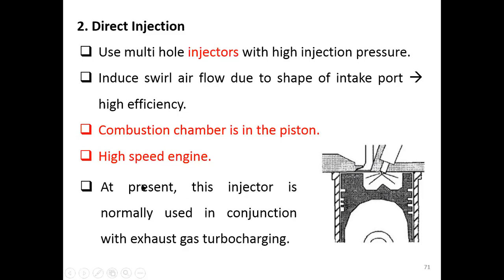Apart from that, this injector is normally used in conjunction with exhaust gas turbocharging. Since the fuel is injected at high pressure, the amount of air that flows in has to be able to catch up with the fuel.